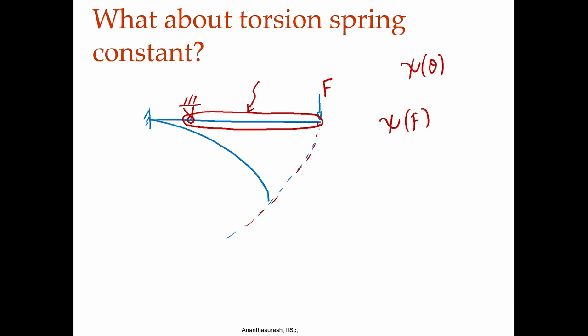This is my equivalent rigid body model. Now, if I show just like this, that is if I just say that I have a crank of length 5/6 L, right, and apply a force, it is just going to rotate. We have to go to dynamics, right. It is not going to settle at some point like the cantilever beam would do, because this lacks an elastic element. So, what we say is that since it is a crank, we can imagine that there is a torsional spring, okay, this is the torsion spring or rotational spring.